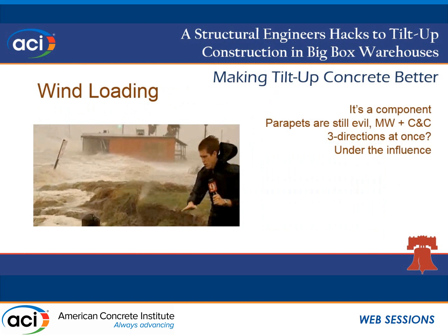Wind load. I've designed a few buildings in high wind regions, so I'm not an expert in wind, but I've dabbled. First thing I will say is, in looking at panel design, individual panels, individual components within a panel, I always treat a panel for components and cladding wind.